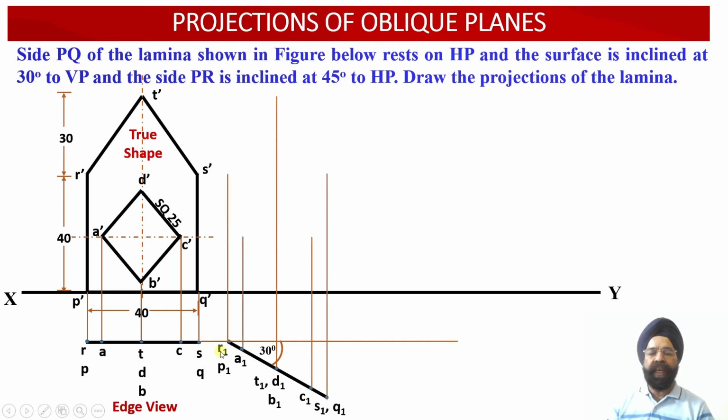Now here you can see, corresponding to these 9 points we have drawn 5 vertical projector lines from these plan projection points into the elevation projection view. Now we are going to draw the horizontal projector lines from these 9 points in such a way that the horizontal projector corresponding to a point should intersect with the vertical projector line corresponding to the plan projection of that particular point.